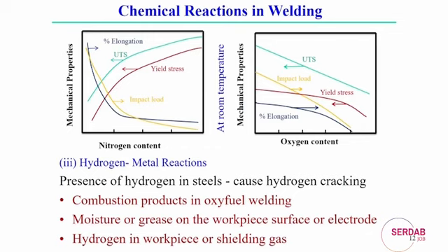So that means the mechanical properties are not beneficial if the oxygen content is high. The objective can be to keep oxygen content to a minimum, but allow some moderate amount of nitrogen, which actually helps improve the weld joint strength, at least in the case of fusion welding processes.